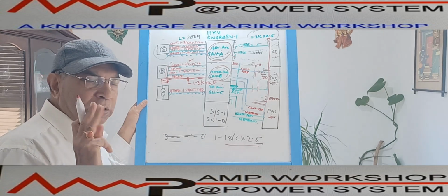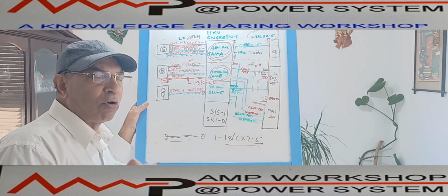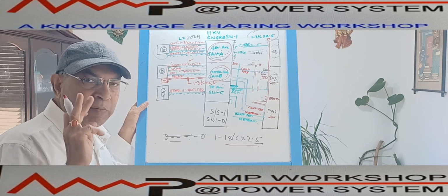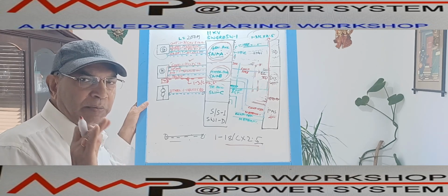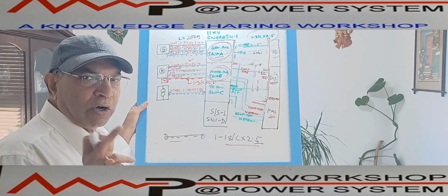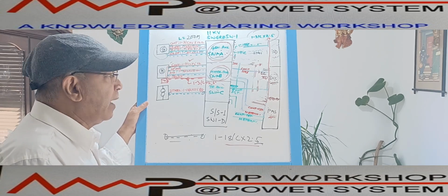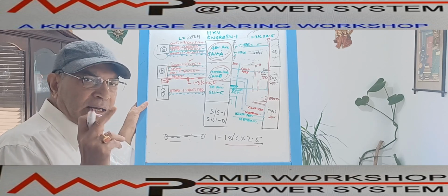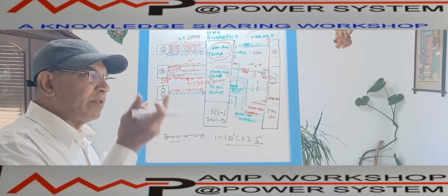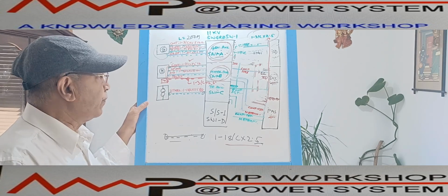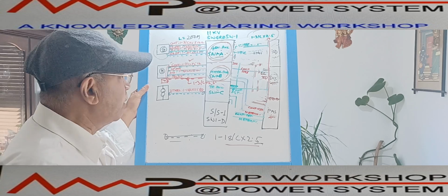So there are two. Normally the emergency push button cable we always lay separately, as it is for emergency purposes. We do not mix it with the other cable. It is a separate cable. So the emergency push button has one control cable for the emergency stop, and in addition to this, another control cable for the circuit breaker on and off, for the local starting and local stopping of the motor.